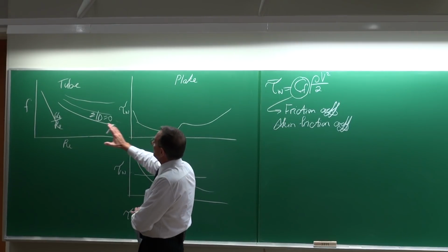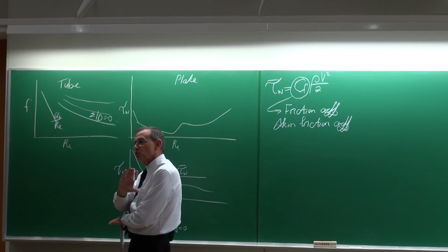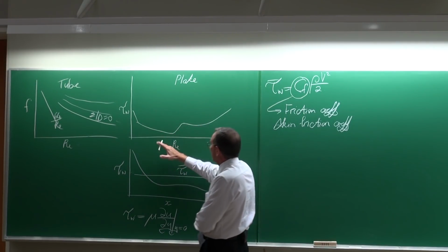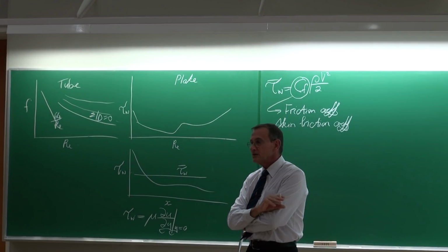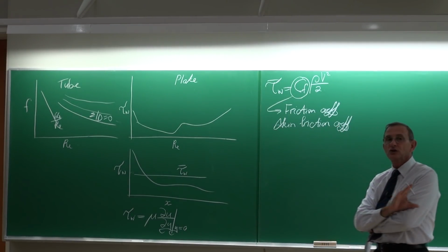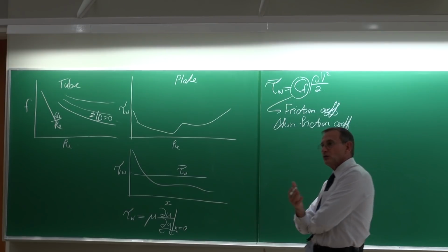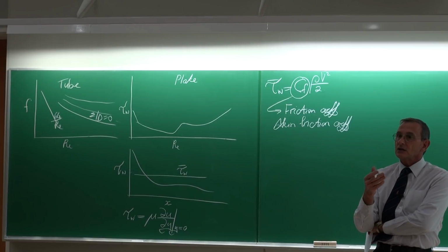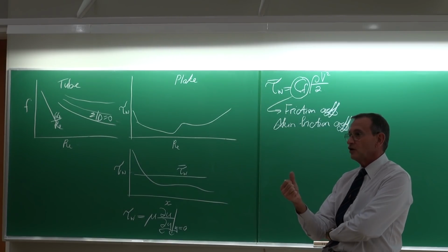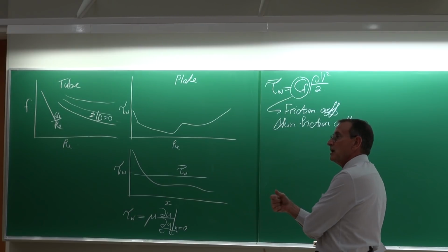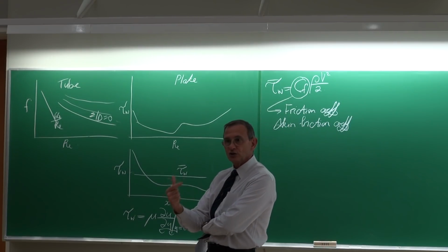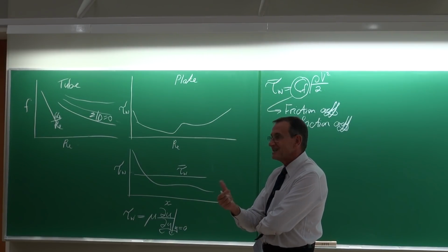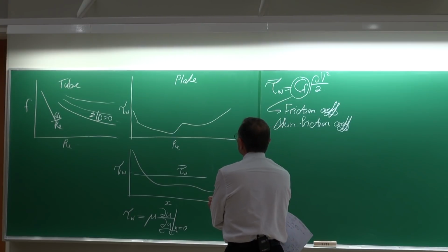Why do we look at something like the friction factor in a course like heat transfer, as well as the shear stress over a flat plate, how it varies as a function of Reynolds number? Because I'm going to show you later on that in heat transfer, many of the practical problems we are going to ask you is you will have to determine the heat transfer rate, the heat capacity of the heat exchanger, but also the pressure drop, because those are the two things that we are normally interested in, and they are in all cases actually connected to each other.